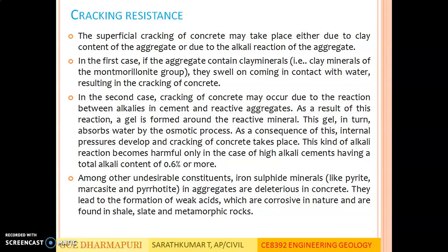In the second case, cracking of concrete may occur due to the reaction between alkalis in cement and reactive aggregates. As a result of this reaction, a gel is formed around the reactive mineral. This gel in turn absorbs water by the osmotic process. As a consequence, internal pressures develop and cracking of concrete takes place. This kind of alkali reaction becomes harmful only in the case of high alkali cements having a total alkali content of 0.6 or more. Among other undesirable constituents are